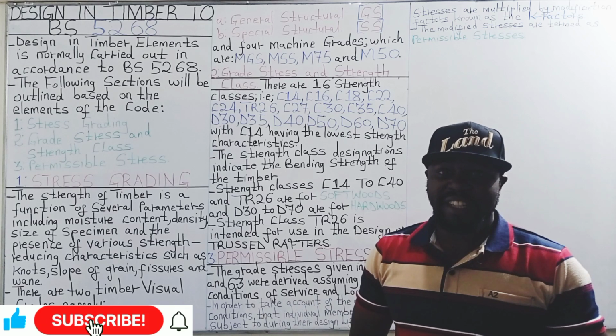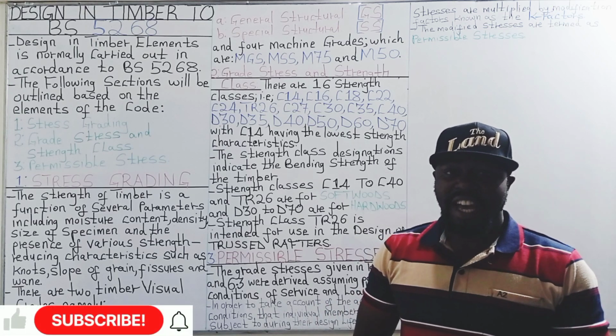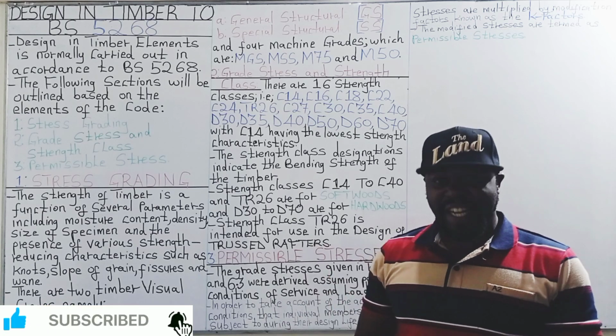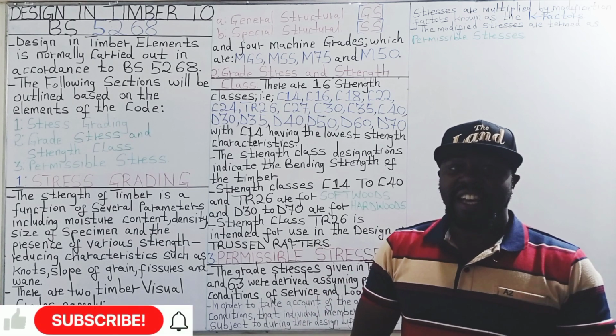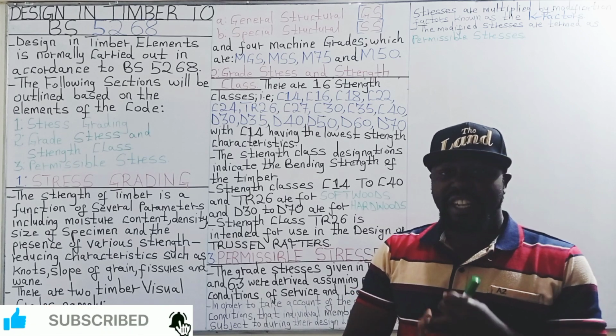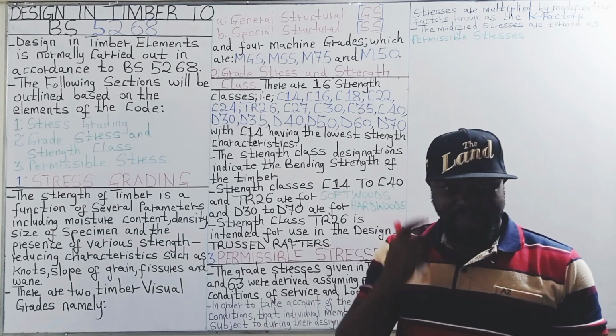Design of timber elements is normally carried out in accordance with BS 5268, and the following sections will be outlined based on the contents of the code. This includes the stress grading, the grade stress and strength class, and the permissible stresses.